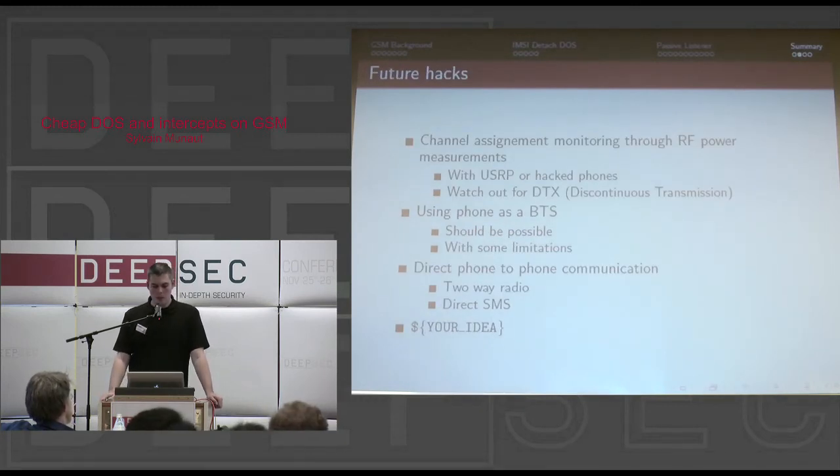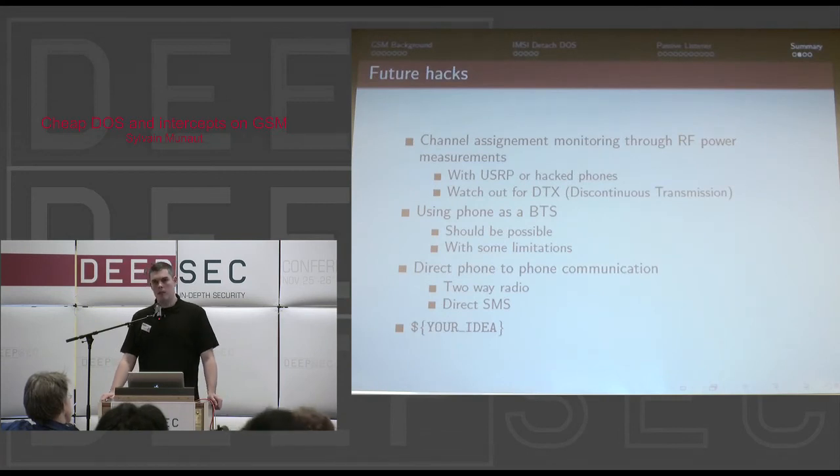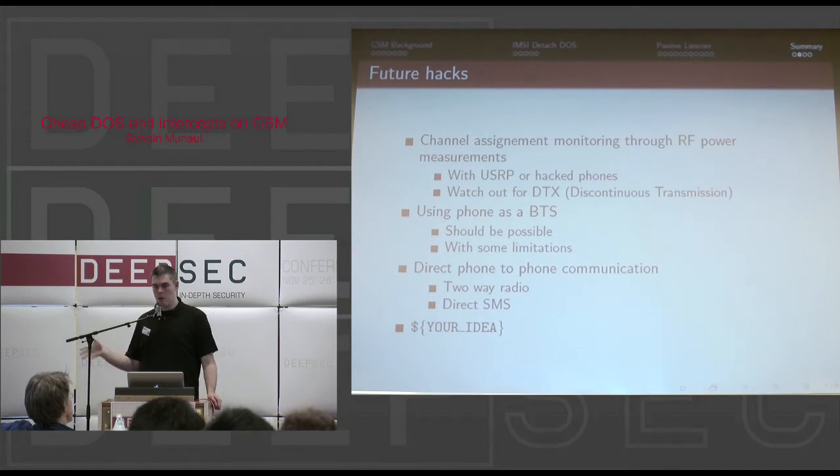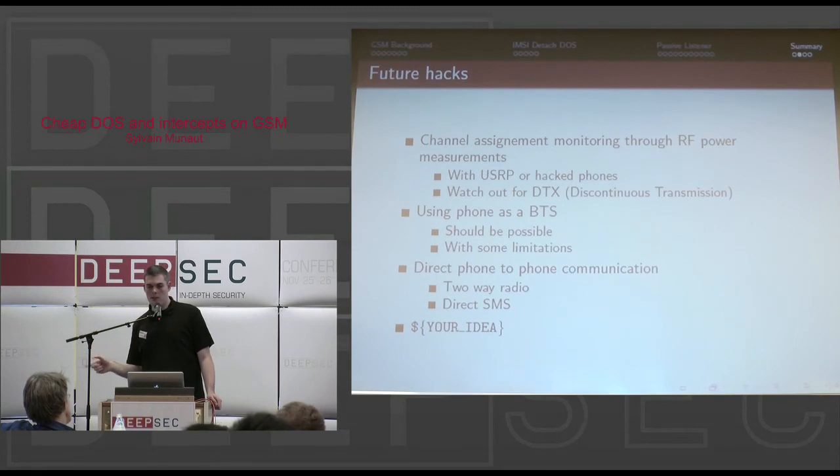What kind of stuff could you do in the future? One problem that happens a lot if you try to listen to a commercial network is that the phone doesn't directly go to the voice channel. It's sent to a control channel, and then the ciphering is enabled, and when the phone is actually answered, you get switched to a voice channel. This has caused some problems if you want to actually listen to the voice calls, because the assignment to the voice channels is transmitted ciphered, so you'd have to crack it very, very fast if you want to follow it.